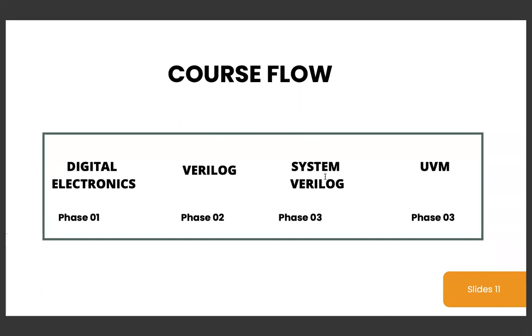Third thing is SystemVerilog, which has a similar structure to Verilog. It's a verification HDL, and it is used to verify whatever design you have written, using different test cases, creating scenarios and so on. On top of that, if you want to structure the SystemVerilog code or verification, there is something called the Universal Verification Methodology, UVM, which is universally accepted.